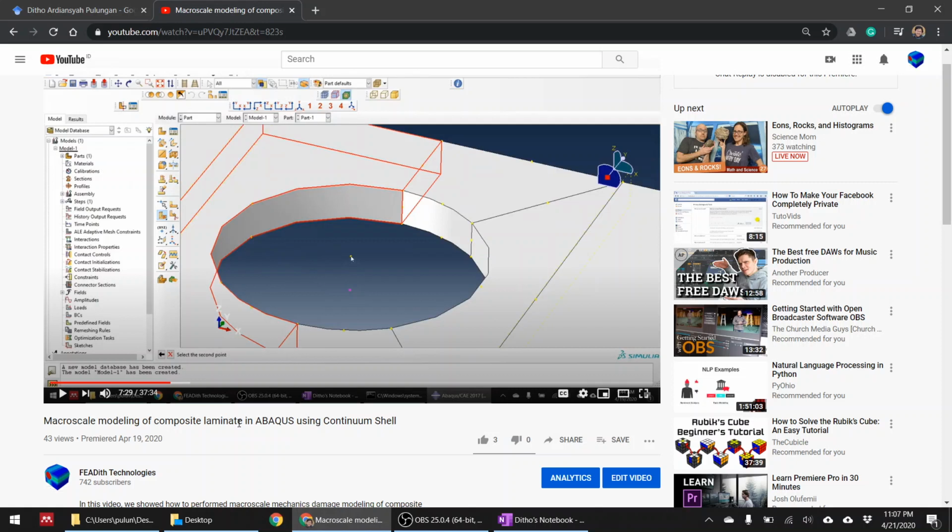in today's tutorial, we will be able to simulate the delaminations because now each ply is modeled explicitly. So if you are interested in seeing how the delaminations occur, and how the transverse cracking affects the delaminations, you need to go to this scale, the mesoscale, where the plies are modeled explicitly. This is the scale that you want to target, not the macro scale.